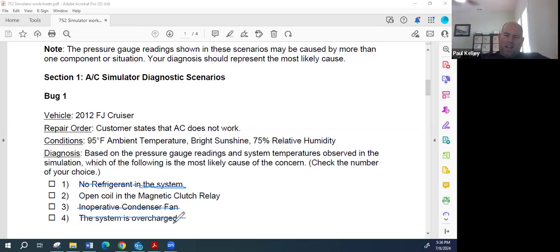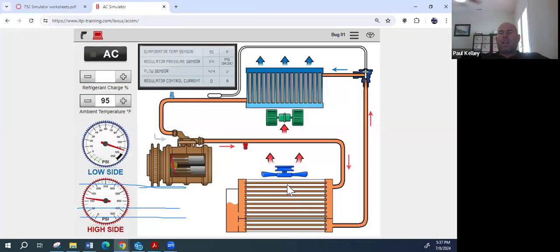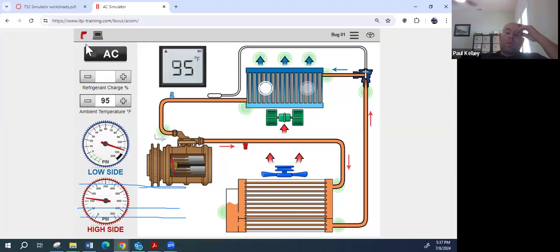I mean, in real life, look at it, right? On this, we actually can't necessarily look at it, but if that fan was open, what would happen? And you're right, the fan being open generally won't affect anything to do with the compressor. But if that fan was open, what might I notice? First off, it's not going to cause the compressor clutch not to work. But if the compressor clutch was operating and it was just a fan, the engine would tend to be overheating,